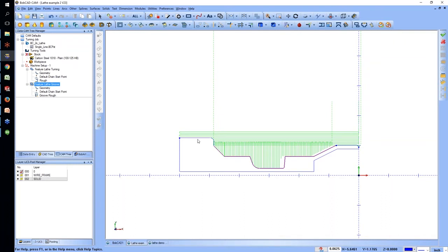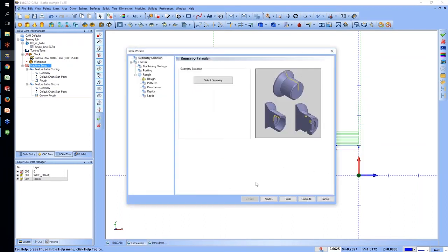Now, the nice part about the system is that sometimes you run into a scenario where, when you were trying to do an inner diameter cut, it was somewhat difficult to select certain things and get the toolpath to really cut the way you wanted it to. What you're able to do is right-click on Machine Setup, and with the new options in the feature settings, when you select the geometry here and here, right-click OK.